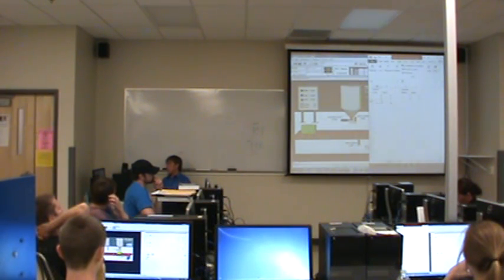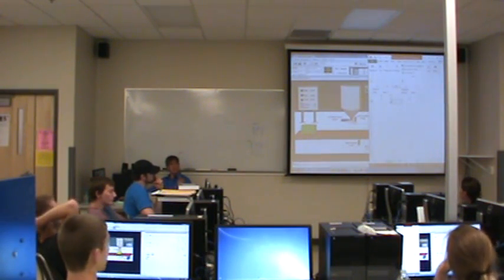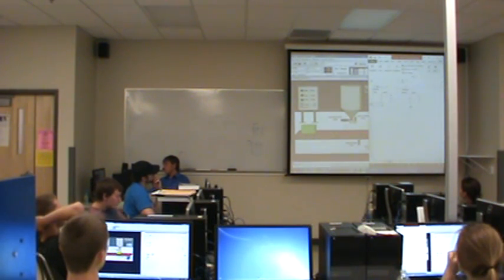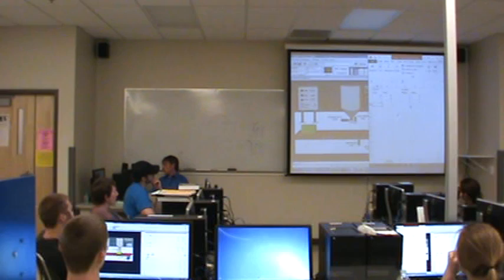What would you expect to see happen next? A full box. Right? Because eventually we'll get to the point where both of those are true. Let me go to that. At that point, what should we do? Turn on the motor, turn off the valve. What would we see happen next? Level false, prox. That's one option. Another option is prox true, level not true.